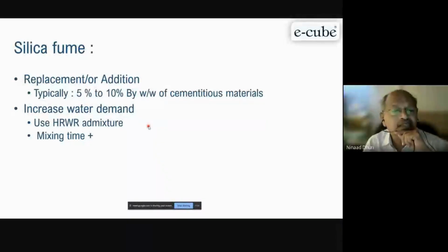So we used only sulfonated naphthalene formaldehyde, SNF based material, but a very high range of SNF, and we experimented for up to 6 months to get that particular admixture, because I designed that M75 concrete for the JJ flyover. We had the batching plant at Vadala, and from there we had to transport the concrete to Bendi Bazar, which is a very, very congested area. All the columns you can see there, 8.35-meter height, were cast in one go. There we used this high water reducing agent admixture, but SNF based.